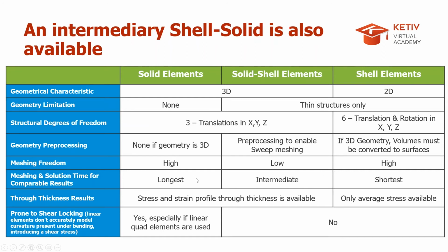It's intermediate between shell elements and solid elements, and if you have mesh sweeping available, it can be another good option.